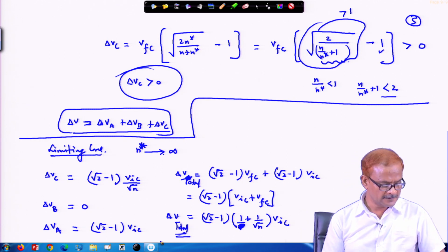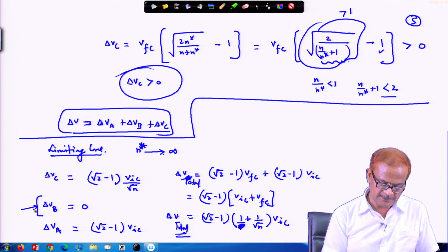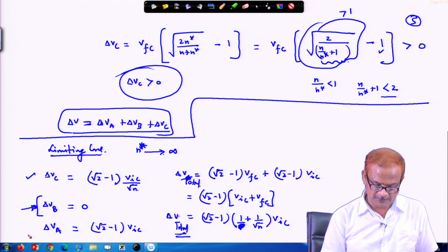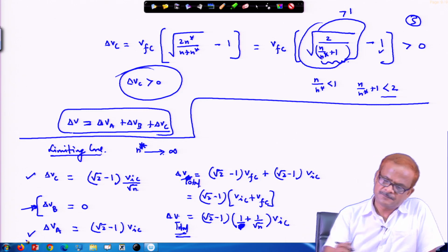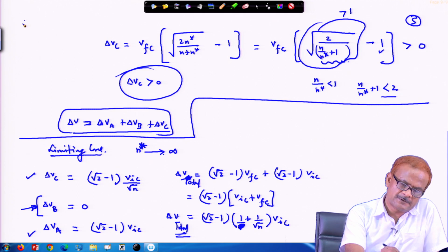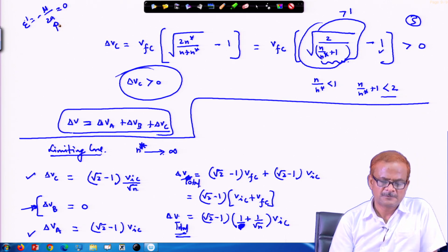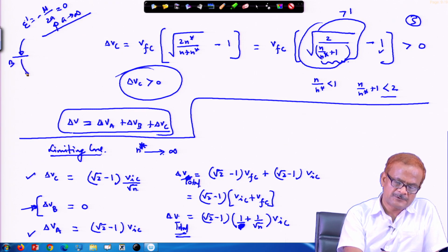Okay, so, this conclusion what we have drawn here, this is important. What we can see is that at B we do not require any impulse. Okay. At C we require impulse and at A we require impulse. Why? Because this is very evident that your E prime equals minus mu by 2 A, as A tends to infinity. So, E prime becomes equal to 0. Okay. A tends to infinity, this quantity is 0. So, approaching from the orbit at B, and then again starting from this place, here the total energy is 0.